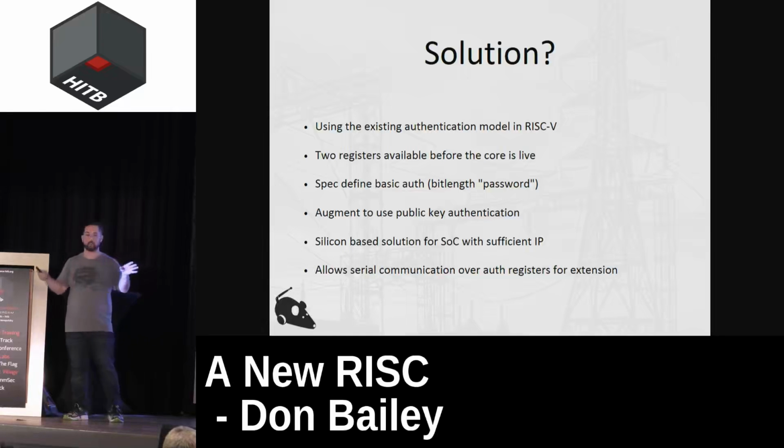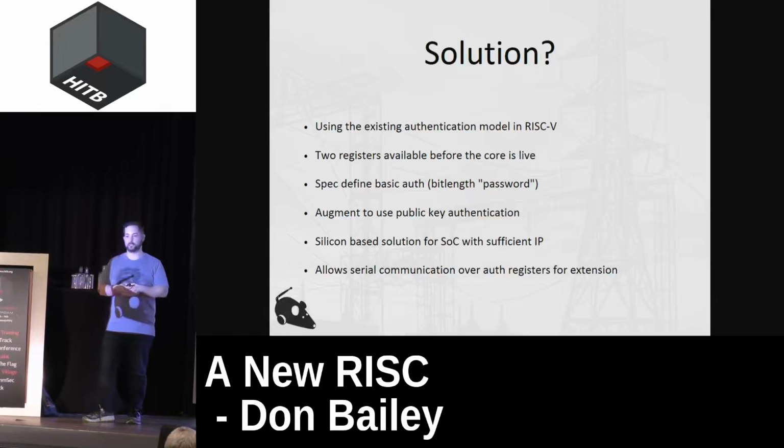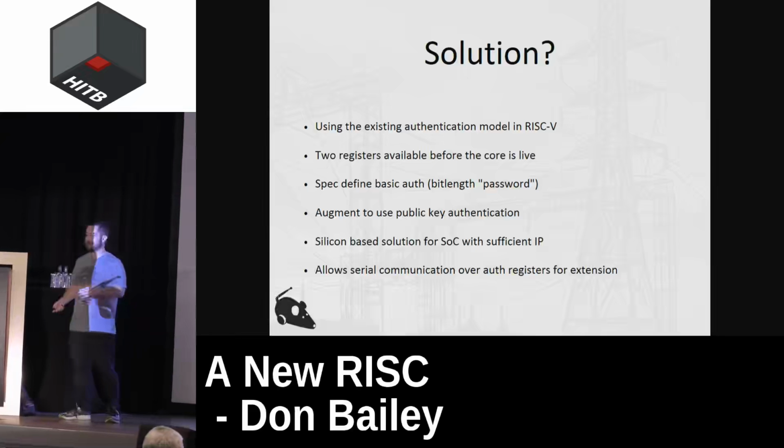So you no longer have this race between when your firmware executes and shutting off JTAG from abusive users. You now have the ability to, at any point in time, validate somebody using public key security that should legitimately have access to that particular set of devices, which is really exciting because that's what we want.